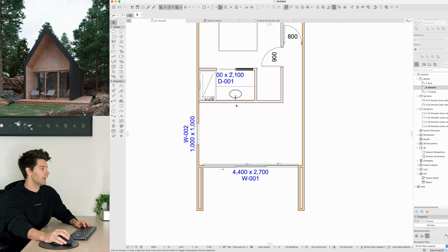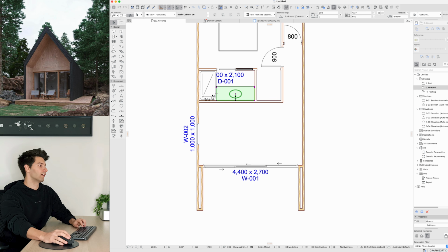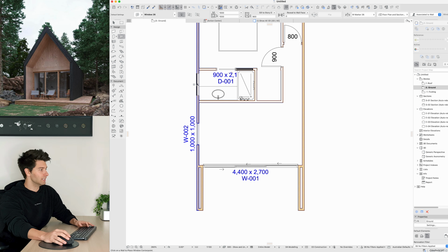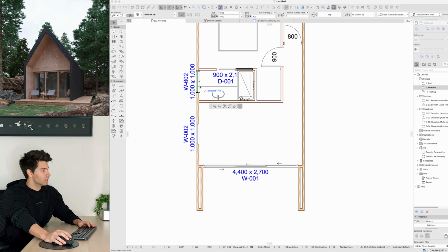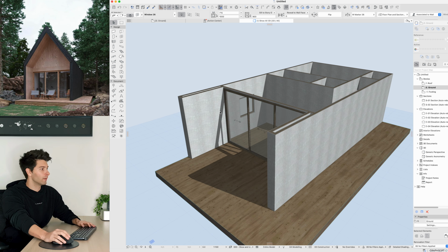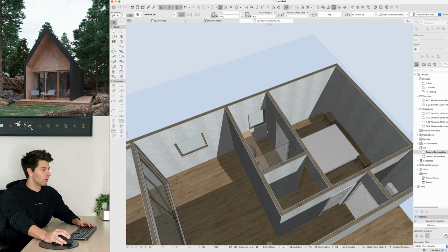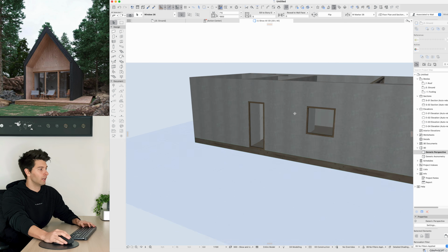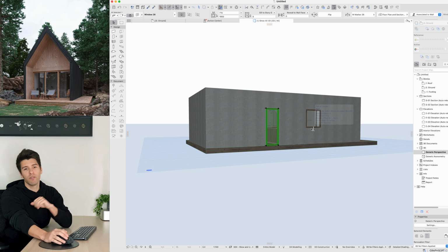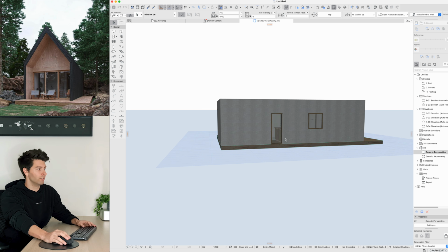Back to our ground floor plan, what I will do is highlight our entire bathroom and mirror that design so that we can actually introduce one more window in this space. If I duplicate that window along the side, select one of the hotspots and adjust the width of it to fit between our vanity and our wall, coming back into our 3D and panning around, we can select that window once again, drag that all the way down, and then look at it from the outside. Provides us with a beautiful, nice fixed frame window.